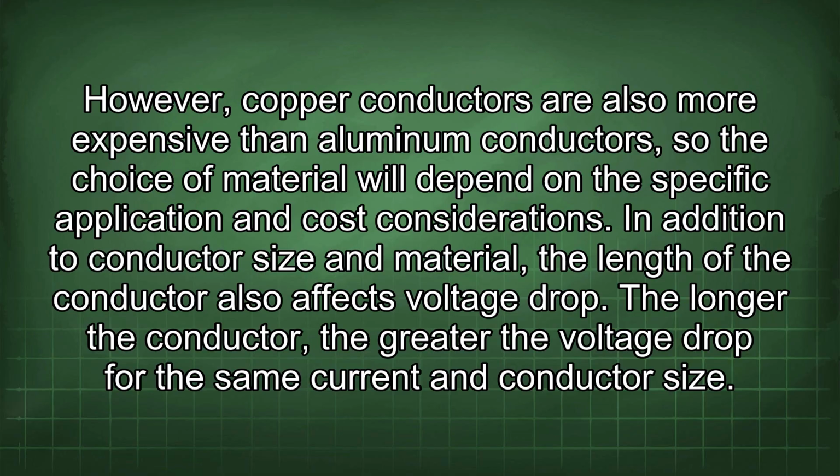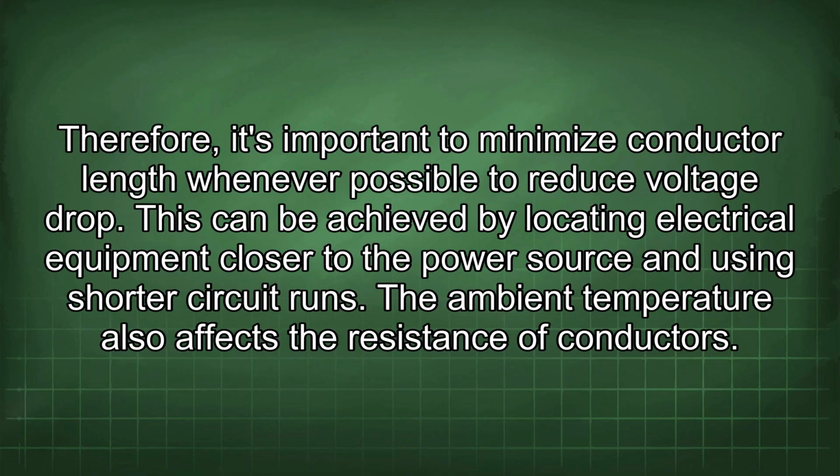The longer the conductor, the greater the voltage drop for the same current and conductor size. Therefore, it's important to minimize conductor length whenever possible to reduce voltage drop. This can be achieved by locating electrical equipment closer to the power source and using shorter circuit runs.